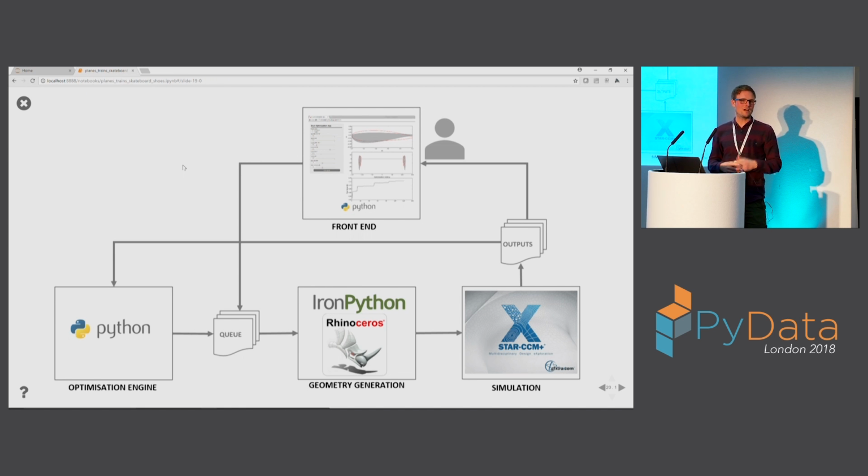So, after 4 hours of running, you can see, oh, has that got better? No, let's leave it for another 4 hours and see what happens. If they see something that's really cool, but think, oh, actually, from my domain knowledge, if I just slightly change the leading radius or the tail geometry a little bit, I can resubmit this back into the queue again. And what happens is that's then picked up by this Gaussian process, it's then picked up by the acquisition function, and you're influencing the optimization routine by having this human in the loop.